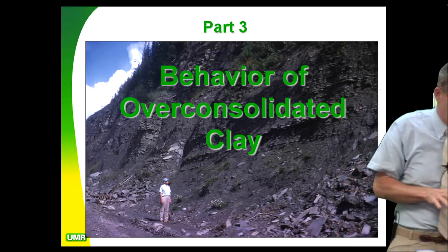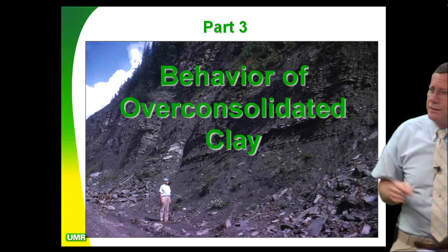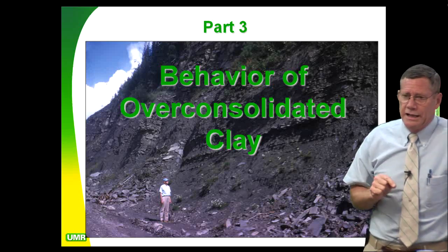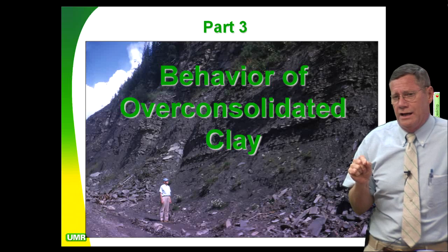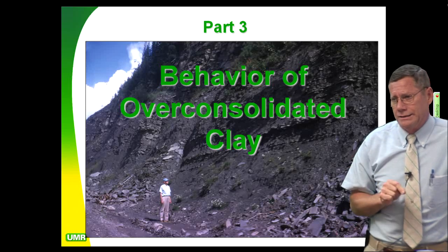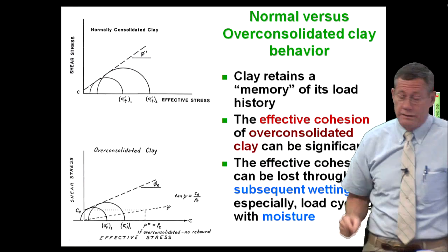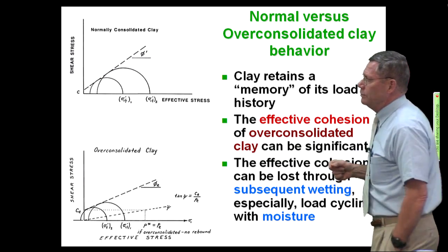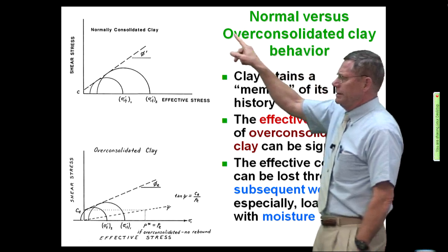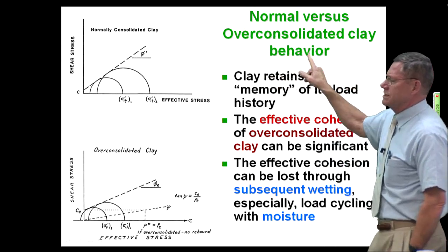It's intelligent material. You can't take too many clay mineralogy courses, because clay is always going to bite you in the behind if you don't understand it. And clay that's overconsolidated tends to lose strength with time. So let's look at normally consolidated versus overconsolidated clay.